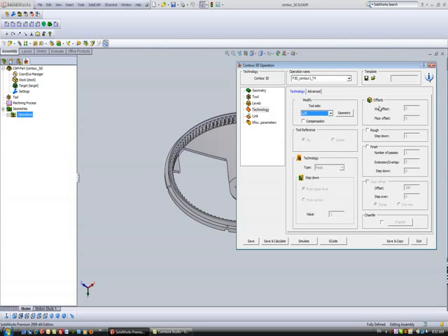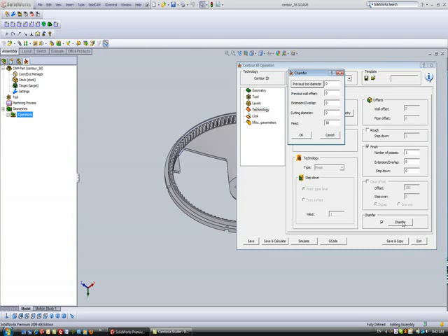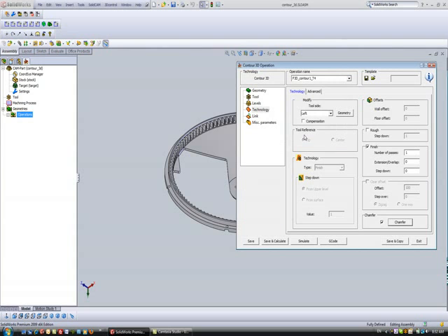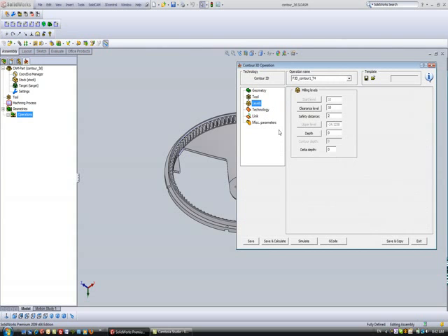Once I do that, these fields over here open, and I'll use the finish option, using the option now of chamfer. This has now been added in. If I go into my chamfer area, I'll simply use 1 millimeter for my cutting diameter of the tool. And if we go back to my levels area, you'll see we have a delta depth.